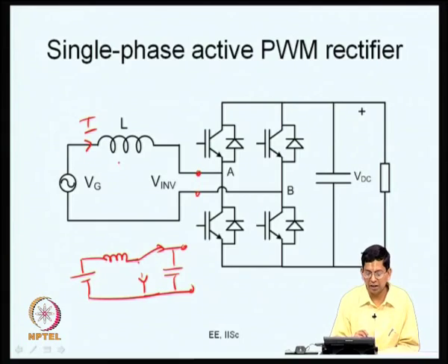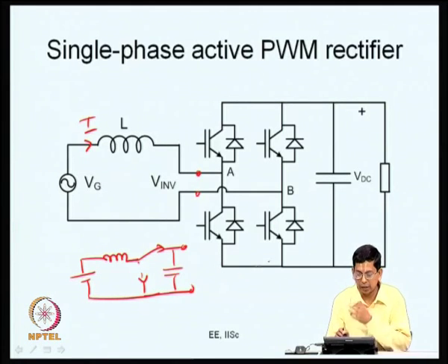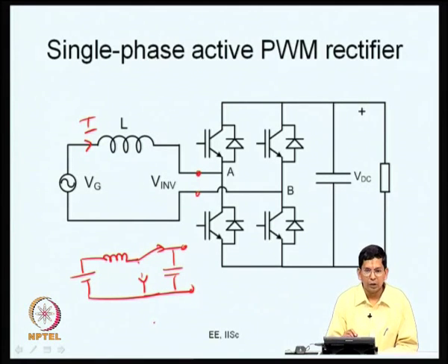You once again have an inductance now. You again have a single pole double throw switch here. At A is the pole, and there are two throws, and you have plus VDC here. The same observations can be made about the other one also. So it is a boost converter. So in a boost converter, what happens now? This is your pole voltage, and these are your throw voltages. Now let us take this negative bus of the DC as the reference.